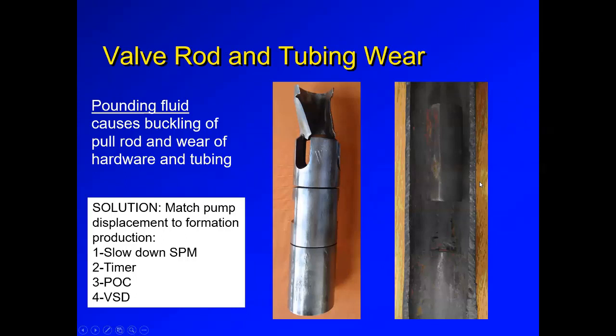There are always problems when you have an incomplete pump fillage. You have rod compression, and the rod buckles, creating all sorts of problems. If you can see here in the picture, probably thousands of times this rod coupling at the same point has been banging the tubing, making the print. You can see actually part of the rod head, and you see the coupling here.